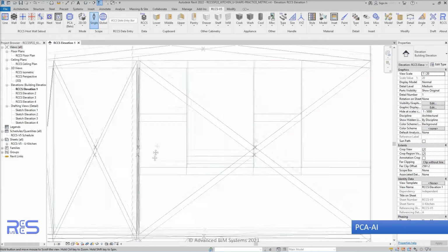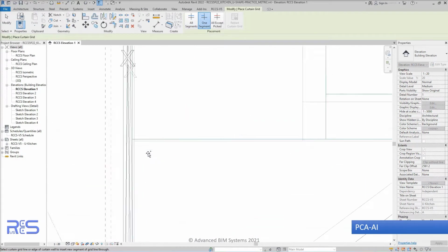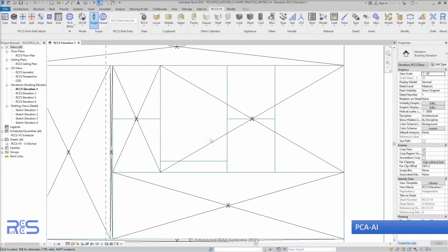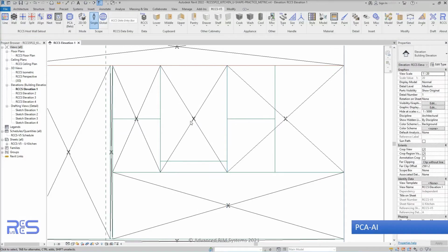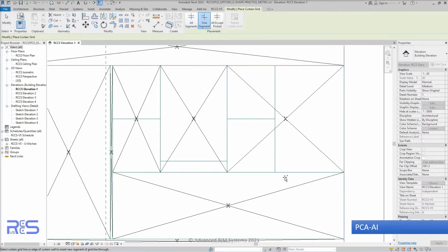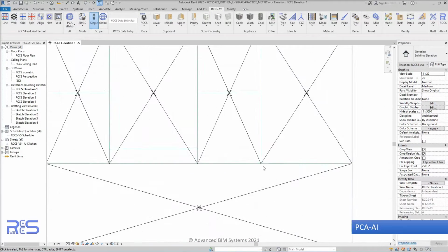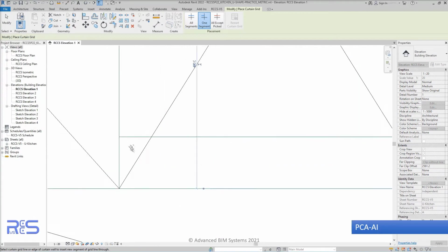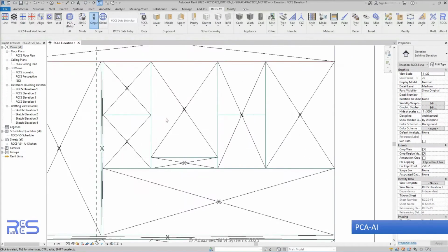Here you can see the align tool being used extensively to create alignments. When they're off, sometimes they're easy, sometimes they're tough to find. Create your grids. Create the splits, split the grids, and use the alignment tool. You'll notice small X's appearing so that you can see where you've created the splits.